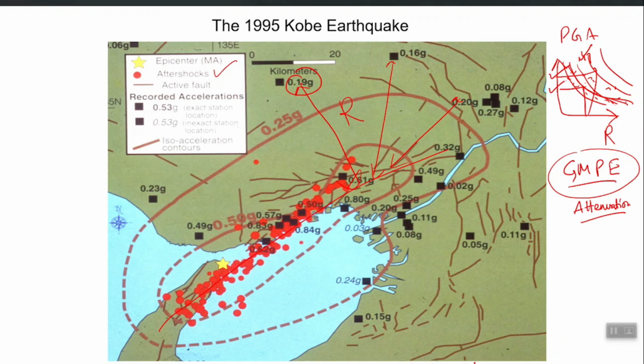I can select a GMPE from literature which is applicable to my seismotectonic environment and do that exercise to predict PGA at my site.